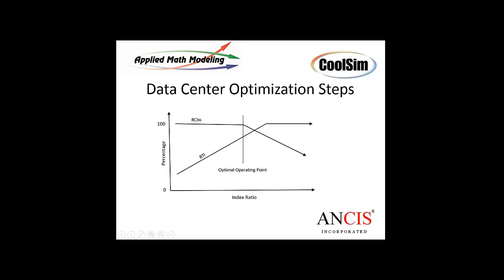And so before I can get to 100% of RTI, before I can get to an even amount supplied equal to the amount required, I start to run into hot spots. And that's exactly what that is showing as it rolls off. So our goal in this next example is to find this point and then to push it to the right by doing air management techniques, and therefore get RTI as high as we can and RCI high as we can.